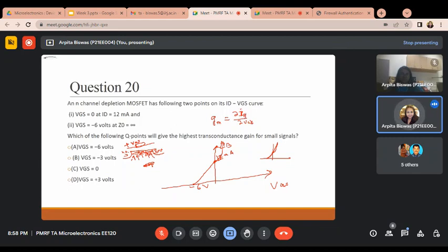And in this region, when you are giving the positive voltage, see here, so already here the N channel is present. Also it will attract more electrons towards the surface, no? So current will increase rapidly in that region when you are giving the positive voltage. So in the positive region only the current will increase rapidly. It means del ID, the change in the current, is increased only when the voltage is positive. Are you getting my point?